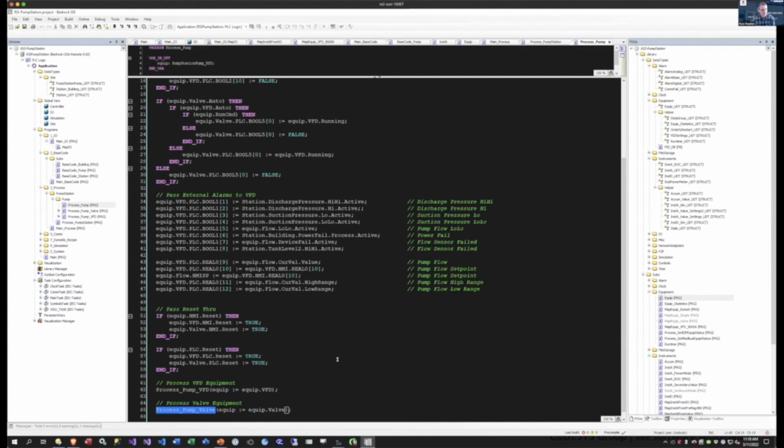And great timing, Tom. So that is one thing I wanted to talk about with troubleshooting this type of program. With function blocks, it's actually pretty easy to troubleshoot a function block because you can open that instance of the function block and actually see all the data.